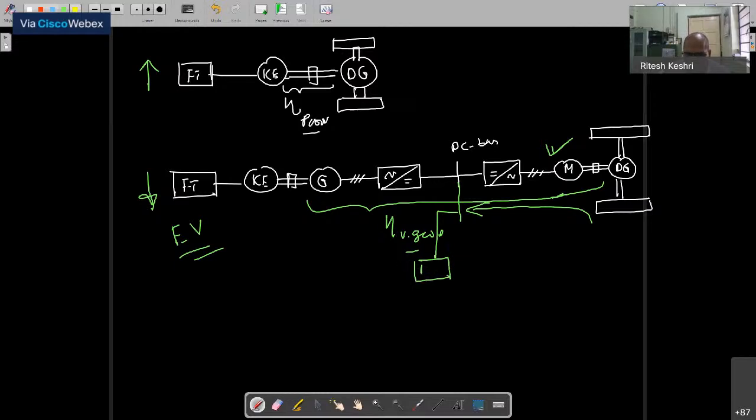So the ultra capacitor is connected with a bidirectional converter. Let's say that this is it. This is something like storing that energy, recovering that energy. So in this way, we have more dimensions to improve the overall performance of the vehicle. By improving the efficiency, you are adding other features such as regeneration in case of electric vehicles. So this is a way in which we are improving the performance. It is not like only this much is there.